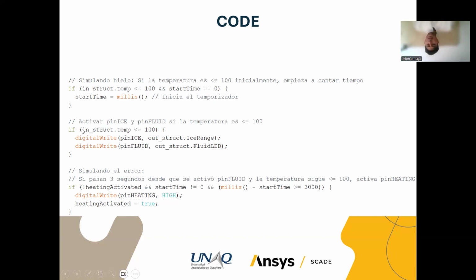So this second subsystem is going to turn on the two LEDs at the beginning because it indicates that there's the presence of ice, and then we're simulating this condition of no rising temperature, when the de-icing fluid distribution system is not enough to raise the temperature.